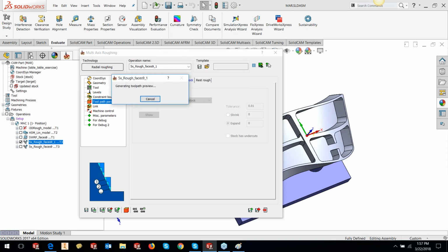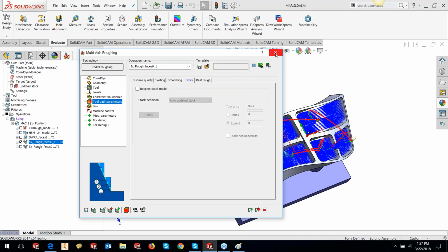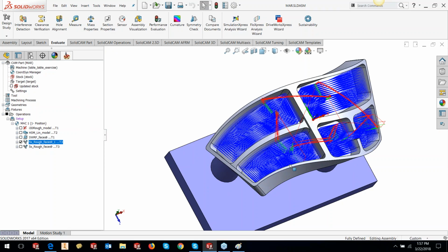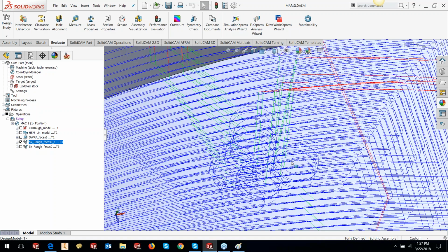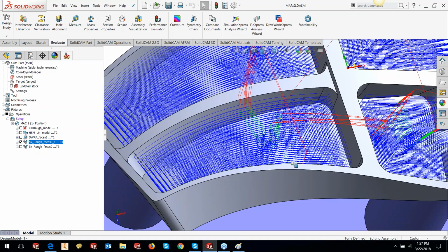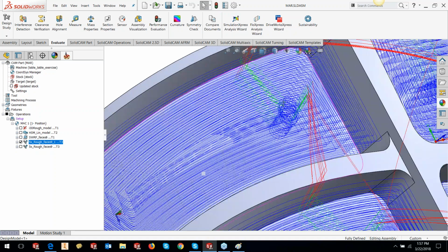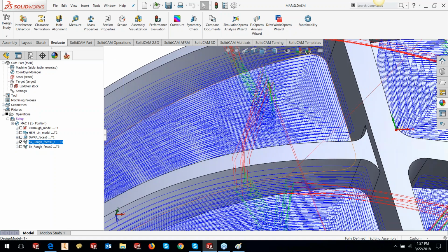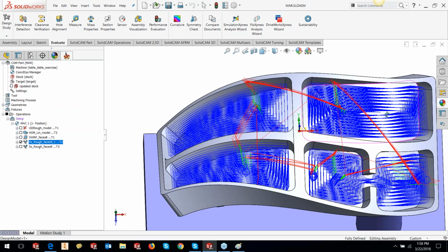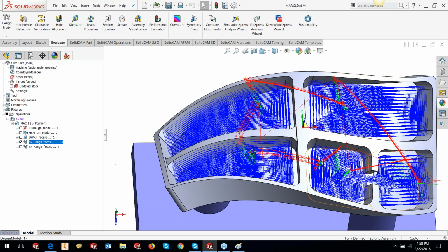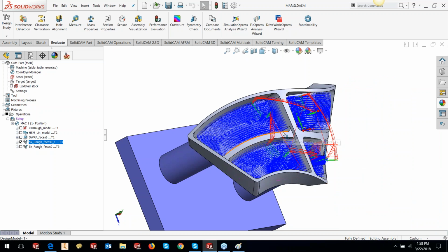All right, this also is done here, and this is how my toolpath looks. You can see that there's a ramp. When it moves from one to the other, again, it is ramping. So it's machining all of this area here. So you can imagine that you could actually use a single pass of this and actually finish the floor of this particular part. Again, this is a very nice strategy.